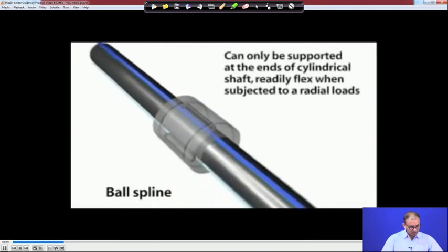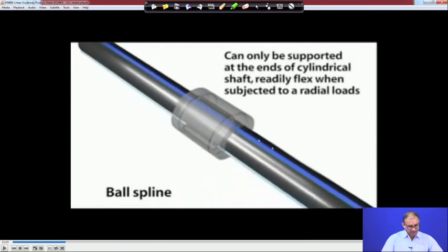Right. So, what was the solution? Instead of a plain shaft, you create one keyway on the shaft. Now, you put the bearing balls on that key part, and then it will create a motion. So, now your balls are restricted to move on a straight line, that means in the linear direction only. When you are moving in terms of torque, it will resist the torque. It is not free to move, because now we have a constrained motion in this axial direction.